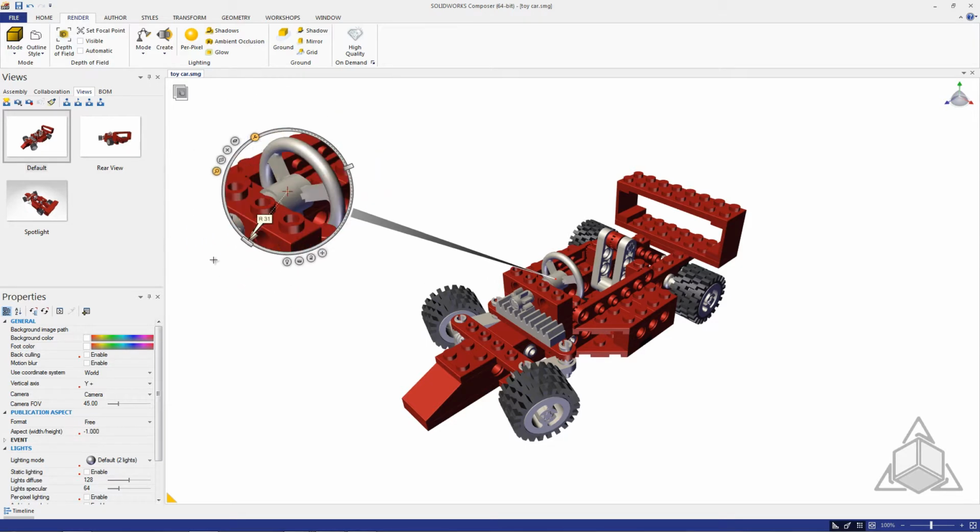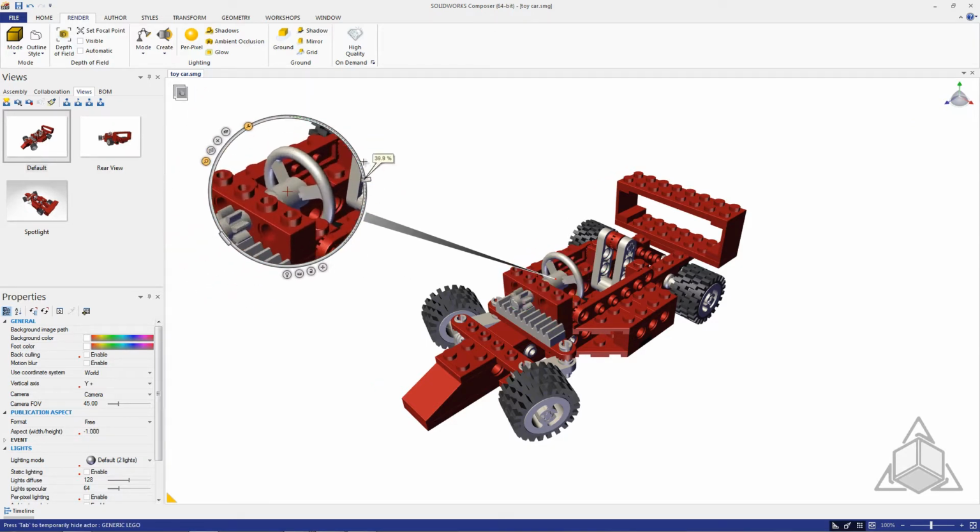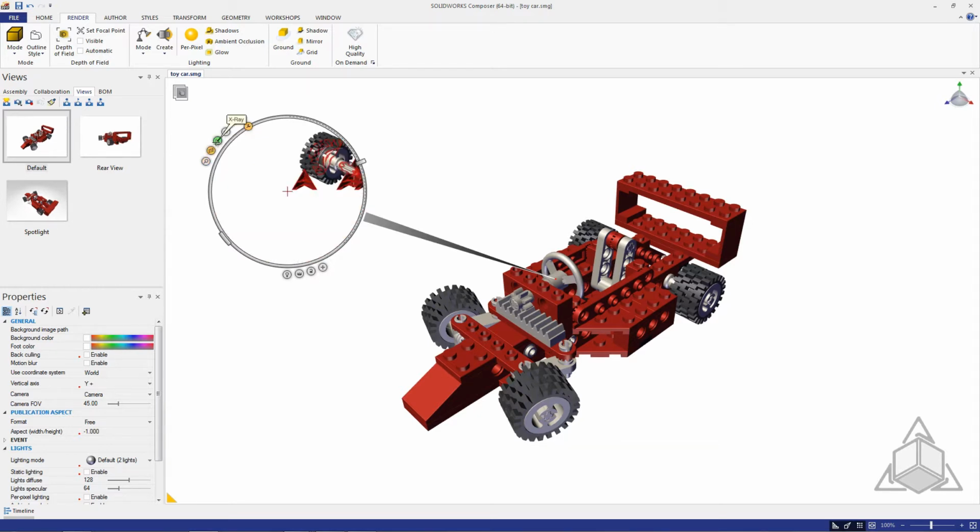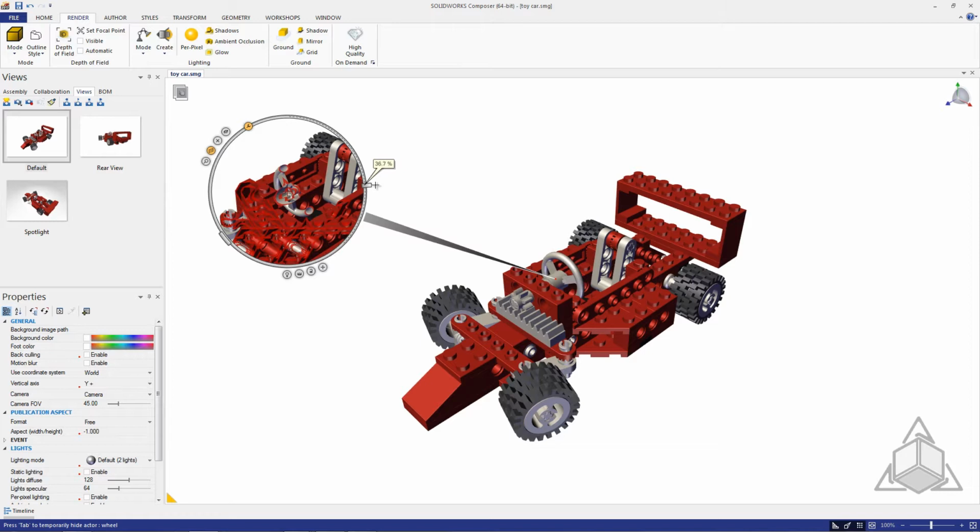Now here is where we can change the radius, and then over on the other side we can change the zoom angle. Now this is because we are on the zoom property. If we take a look at some of the other things, we have cutting plane, X-ray, onion, and onion skin. Now cutting plane takes a plane and it just creates like a section view cut through it.